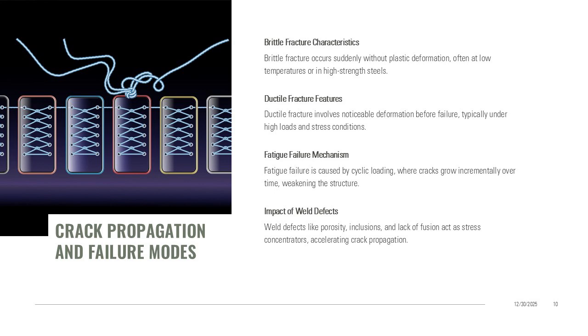Weld defects such as porosity, inclusions, and lack of fusion act as stress concentrators, accelerating crack growth. Understanding these failure modes helps engineers select appropriate materials, welding processes, and inspection techniques to prevent unexpected failures.